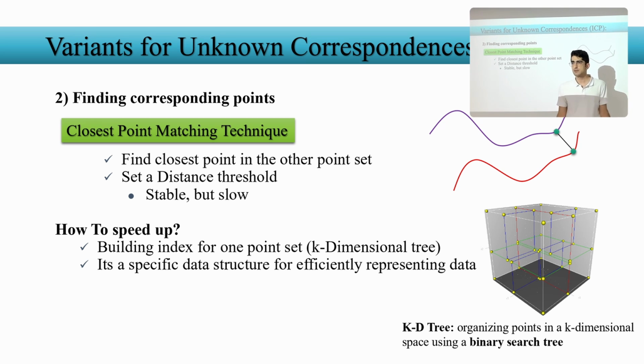Your scan A, as time increases, by default we say it is impossible to jump to another building or somewhere else. I'm somewhere around here, I'm moving somewhere around here. Then I can put a threshold that says, when you're matching the features, match features to the nearby point cloud. The idea comes from there, and this is called the closest point matching technique.